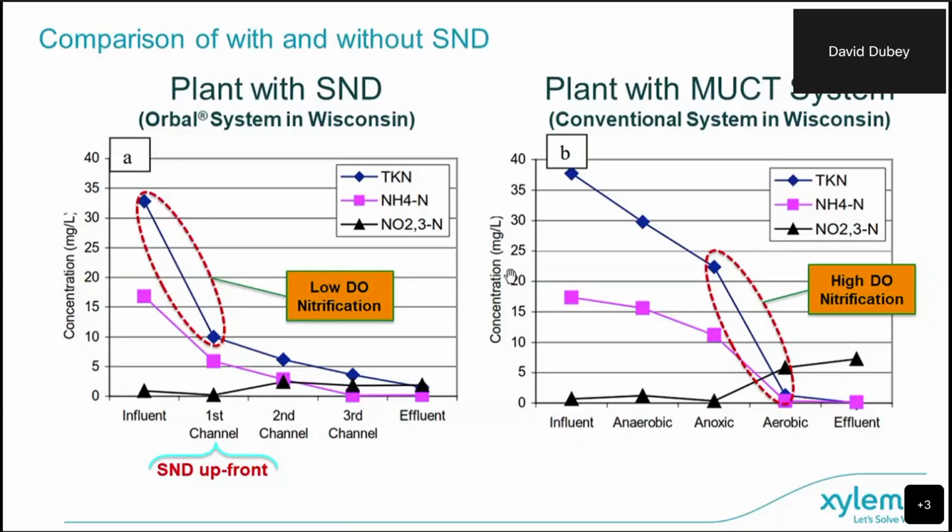If they don't convert any of this ammonia, or only a portion because some of the equipment is down, that ammonia is going to end up in the effluent. As well, they're going to have some higher nitrates. So it's a much better buffer, and it has a better removal. If you look at the total, the sum of the nitrates and the TKN, we're close to 10 here instead of less than 5. And these are 2 actual operating plants.